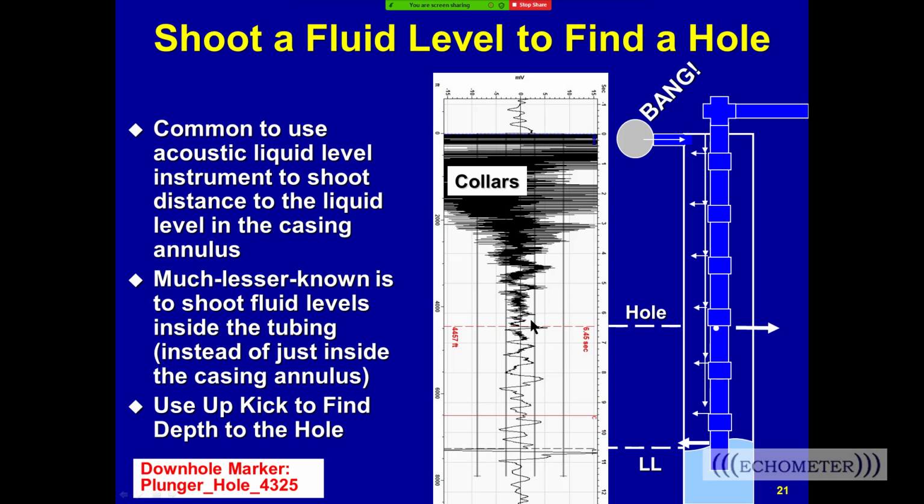Okay, yes. And well, it also made a second question asking if the tubing leak can be detected if the leakage is below the fluid level. Right. So if the hole's below the fluid level, then the well circulates the fluid through the hole, and the liquid levels become close to the same level on the inside and outside, and that's discussed in the paper.